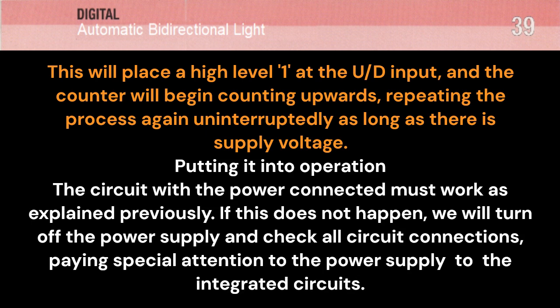Putting it into operation. The circuit with the power connected must work as explained previously. If this does not happen, we will turn off the power supply and check all circuit connections, paying special attention to the power supply to the integrated circuits.